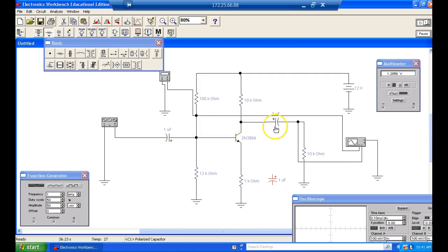So these capacitors are called coupling capacitors, right? Everybody okay? Because they couple the signal in, and then they couple the signal out. They keep the bias in because the capacitors block the DC, right? You understand? This guy right here causes your AC signal to bypass that resistor right there. So instead of the gain being set by this resistor, the gain is set by this thing we call RE prime, which is really, really low.